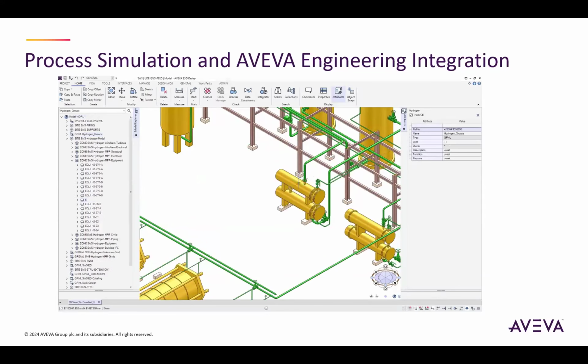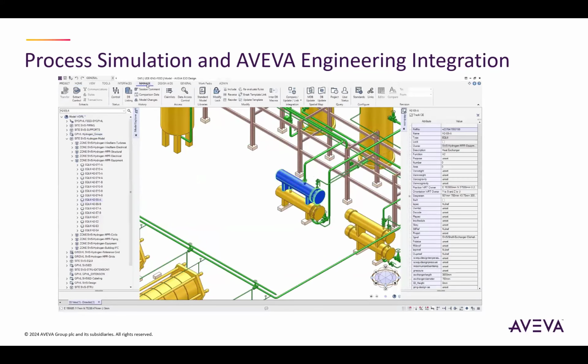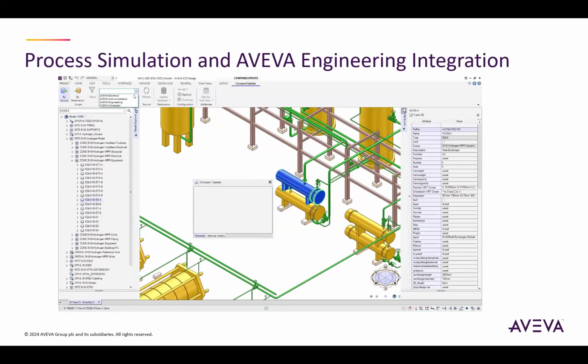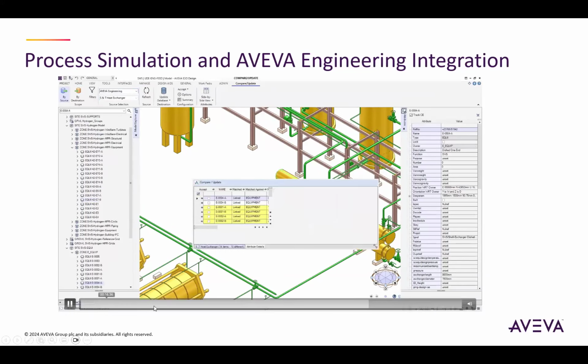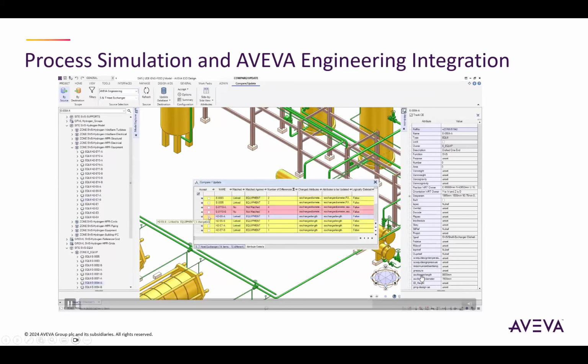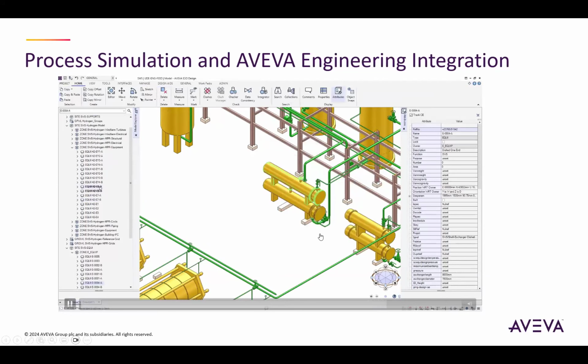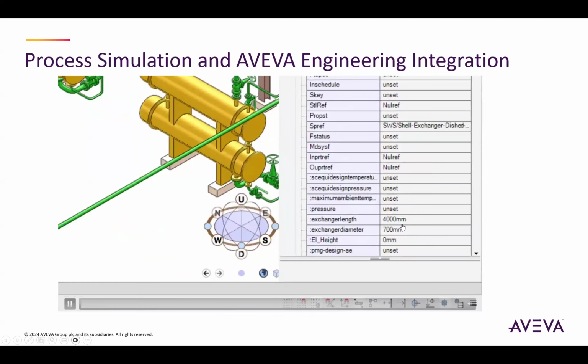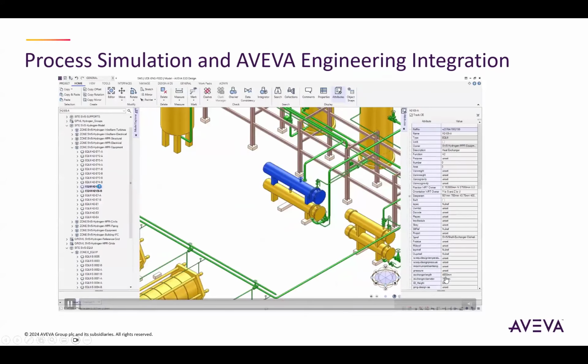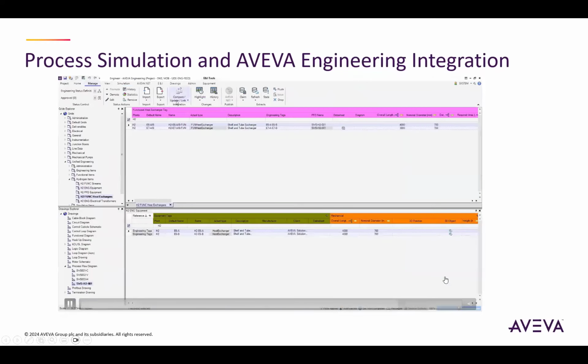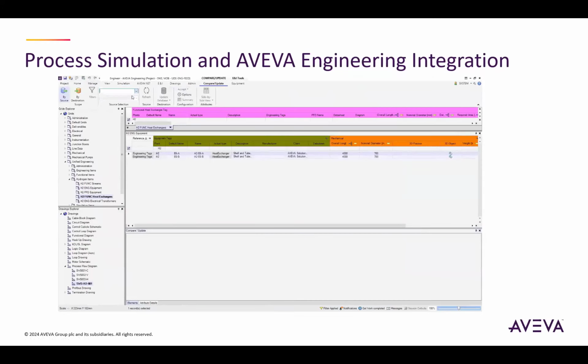ahead and pull the information from the master tag registry with the new changes that were done for the length of the heat exchanger, and accept the information where the heat exchanger is automatically updated from the current length to the new length that was changed by the mechanical process, and now they end up with the new length, the length that was specified by the process engineer.